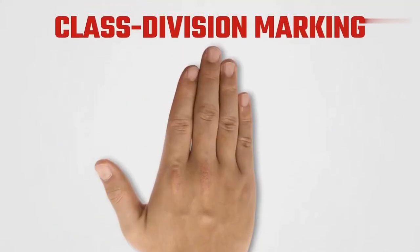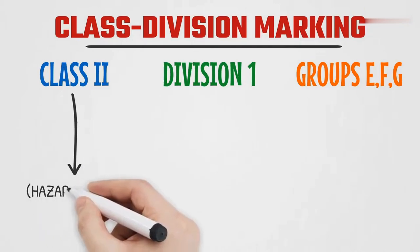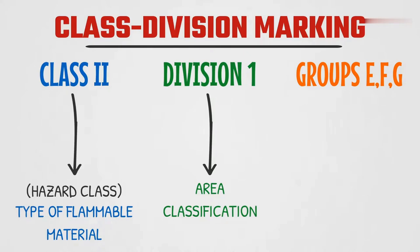A class division marking has 3 main parts, as shown in this example. Class 2, Division 1 groups E, F, G. The first part indicates the type of flammable material, Class 2, which means dusts. The second part, the division, refers to the quantities of the explosive materials present and under what conditions. It can be Division 1 or Division 2. Our example is Division 1 as was explained earlier.